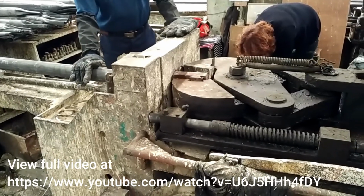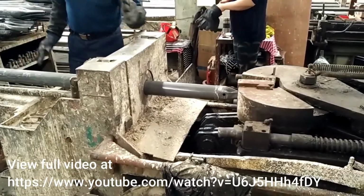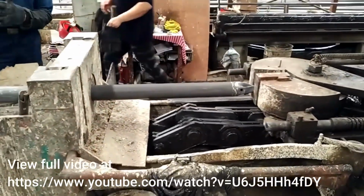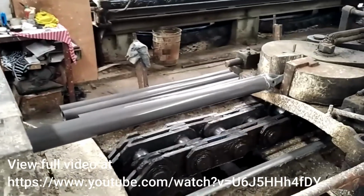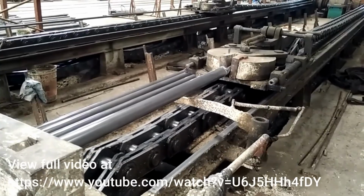Tube steel has the same 4-digit identification that bar does, the most common being 1020 and 1026. Also available in hot rolled and cold finished. There's actually another opportunity there as well. This is drawn over mandrel, or DOM. Now this is very similar to the cold working process. It's different though, where it controls the OD and ID very carefully, and you can get strengths up to 72 KSI yield. These are the most expensive as far as tube steel goes.